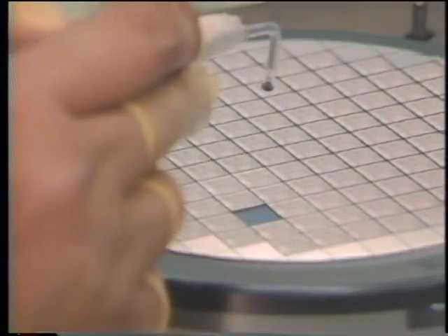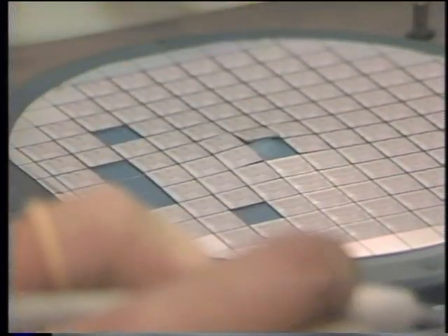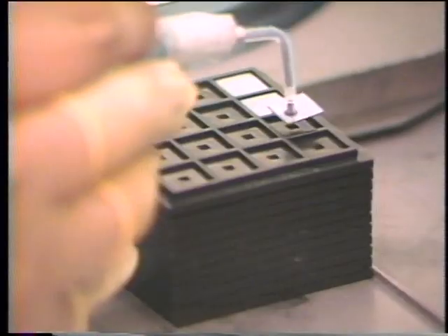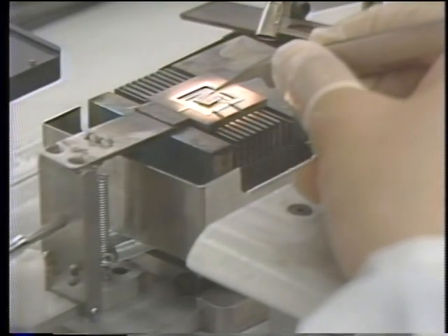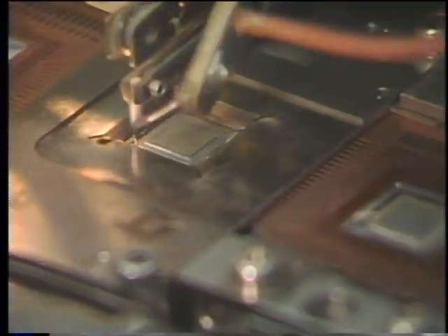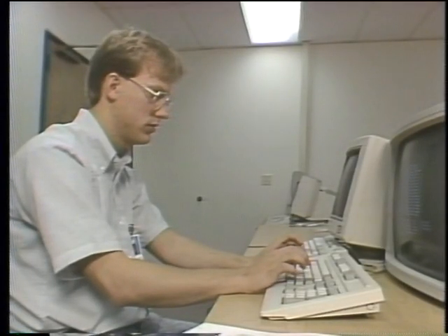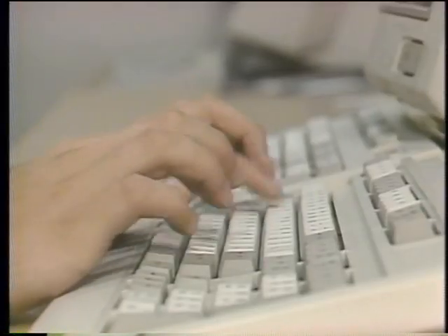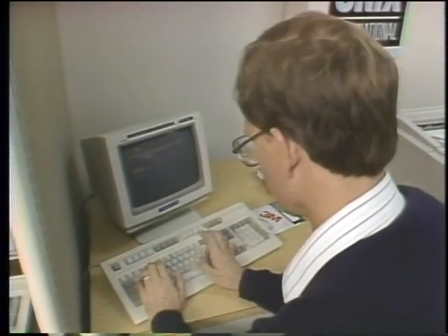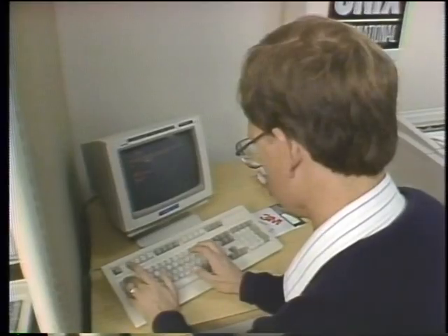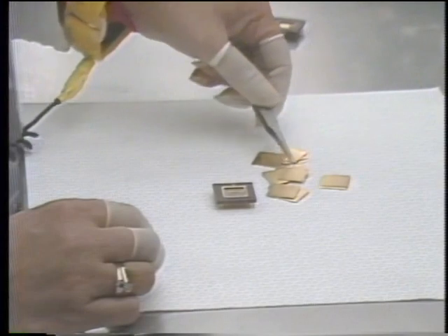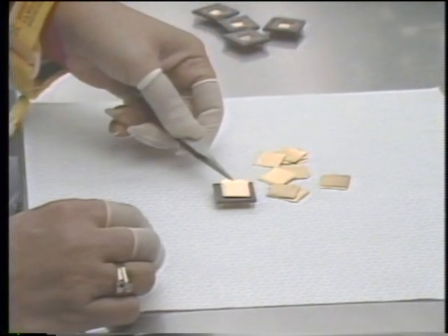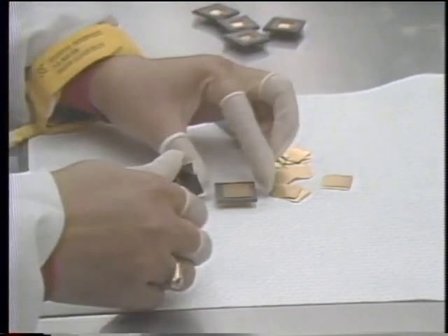Even when Intel brought out the new 286 and 386 chips, the problem still remained. The 286 could address 16 megabytes of RAM, and the 386 can handle 4 gigabytes, but the limitations of existing application software and the lack of a new standard operating environment mean most computer users are still running their 286 and 386 machines like fast 8088s without taking advantage of the access to expanded and extended memory. That's called running your CPU in real mode. To get at the memory space above 1 megabyte, the 286 and 386 chips have to operate in what is called protected mode. Intel's Mike Bemis explains.